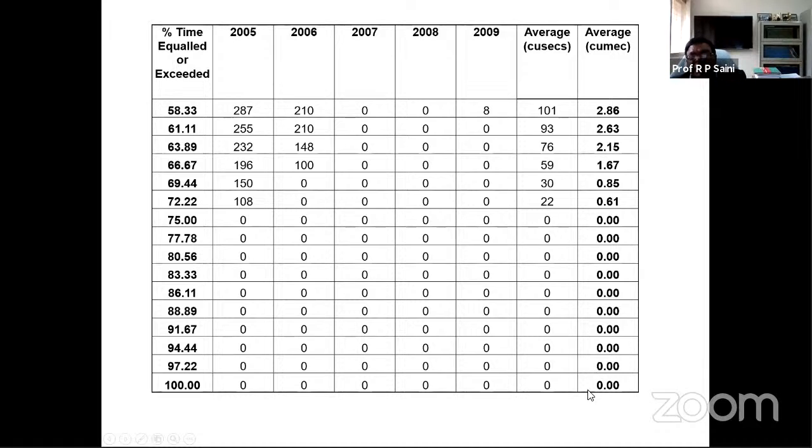That is my concern. I want to know, for a particular discharge, how many percentage of time in a year it will be available. So if somebody asks what value will be available throughout the year for that particular area I'm talking about, of course, this particular example has many zeros, so don't worry about that. But I can say the minimum discharge value will represent the maximum duration.